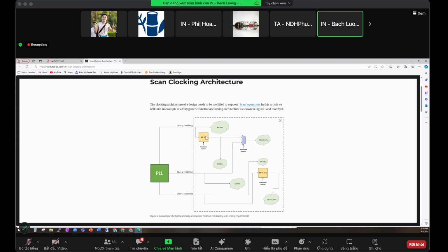Otherwise the tool will stop right here and would not go through this. Or the more standard approach is to create generated clocks here. Right? So they need to know create generated clock. They need to understand that concept, right? Yeah.